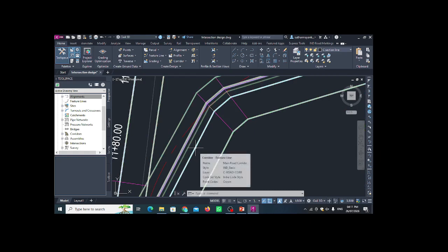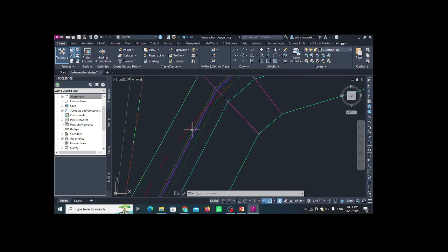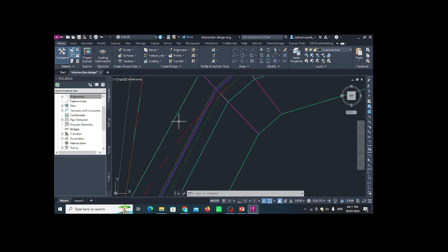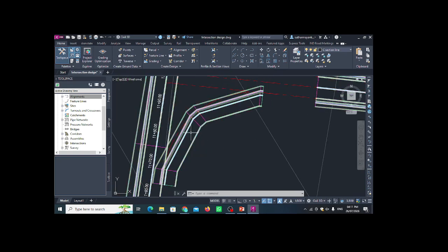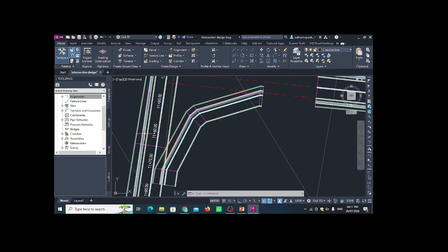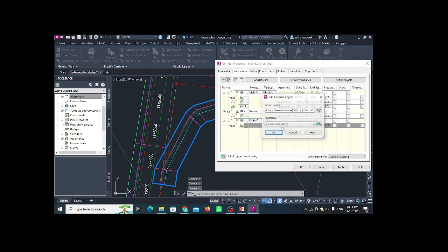So where is the crown part? You can see the crown part is here below side. Okay. But actually we need the crown part at this side, because this side we can see the back curb and gutter and the daylight part. So this is not a right one. So that's why we have to change the assembly properly, and we have to set the assembly property.